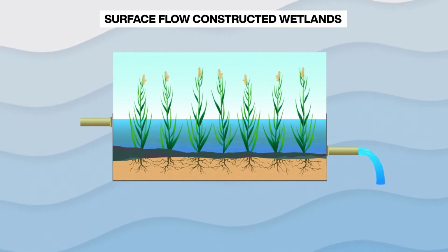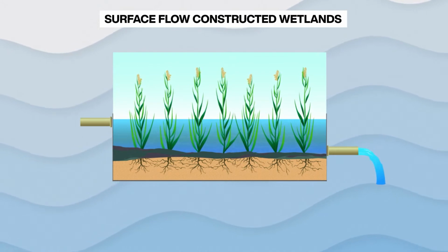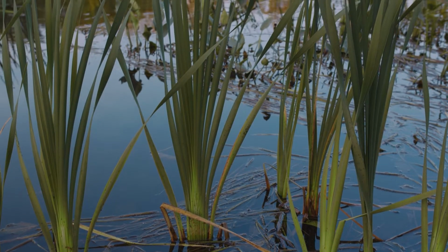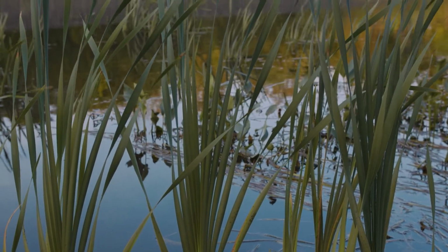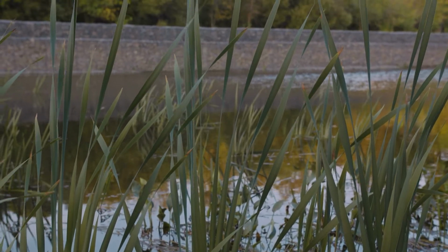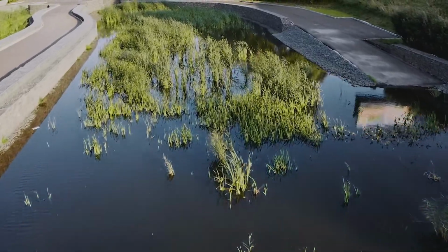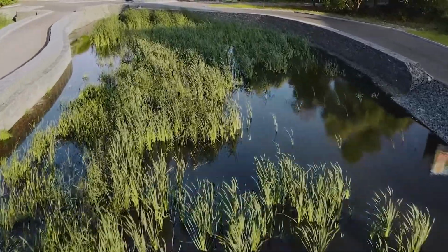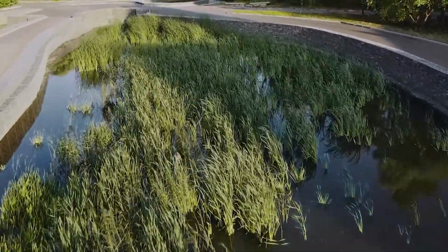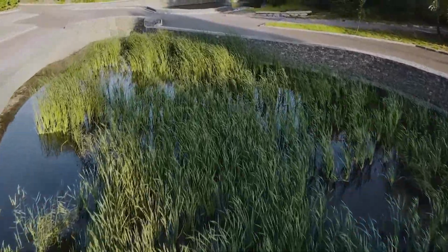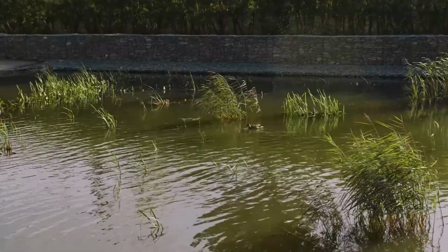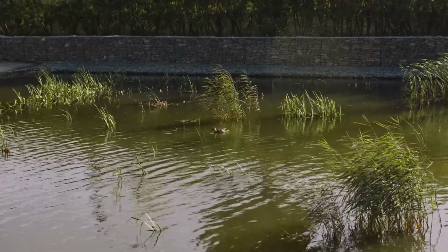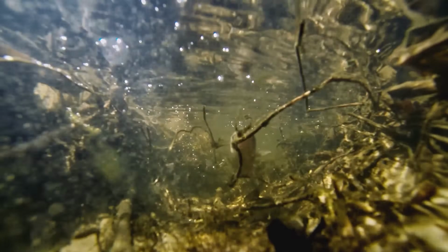Ms. Doolittle, could you please remind me of the basic characteristic of this construction? First, wastewater filtration is performed by plants and not by gravel. Second, they have a dense vegetation to minimize the sunlight on the constructed wetland surface. Why? Because sunlight encourages the development of microalgae, which increases wastewater pollution by suspended solids. Third, it's recommended to populate the constructed wetlands with fish, which helps to decrease the development of mosquito larvae.